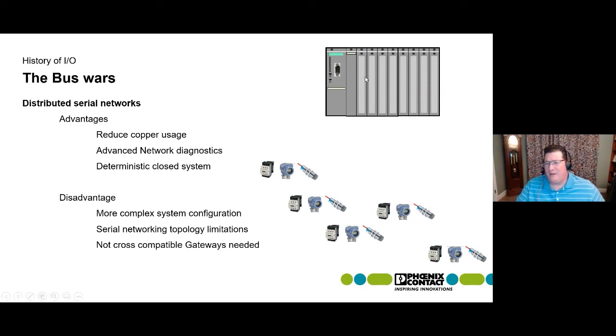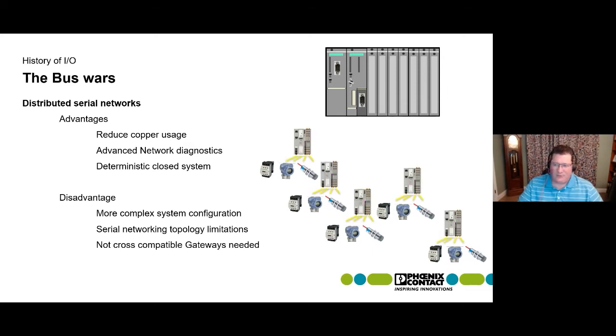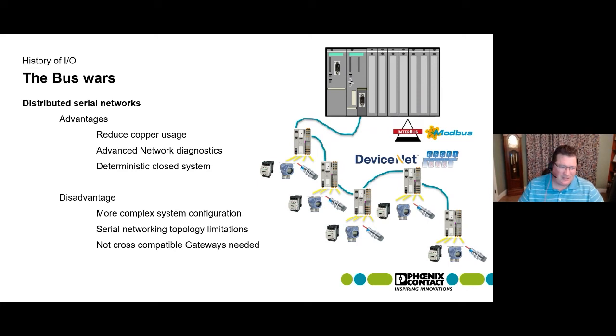Now we're going to replace one or two of these I/O cards, depending on the size of the master, with the new serial communications interface. So it's an I/O card, but instead of having wires to go to I/O signals, it's going to have a serial connector to go out to the network. Then we're going to create a new I/O module that sits directly out in the field, close to the sensor. We're still going to parallel wire all of our I/O signals from the sensor to our new I/O card. But now, instead of those parallel wires running all the way back to the PLC, we're going to bring those bits of data in via parallel wiring, line them up into a serial bit stream, and push them through this cable all the way back up to the PLC.